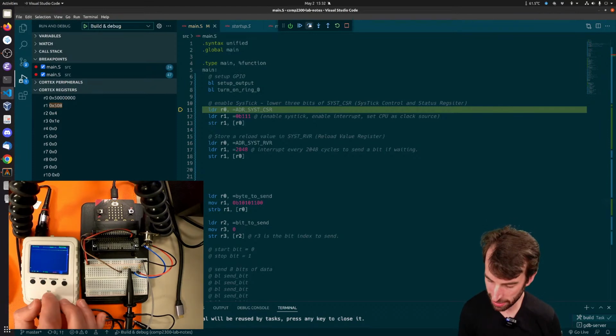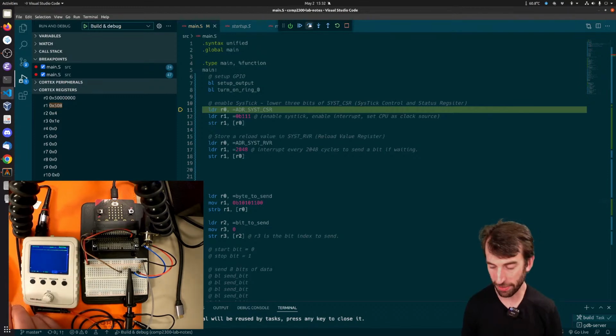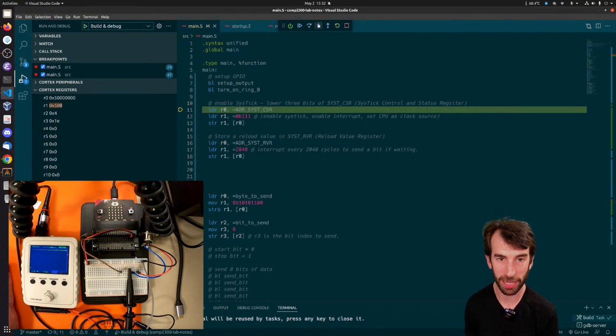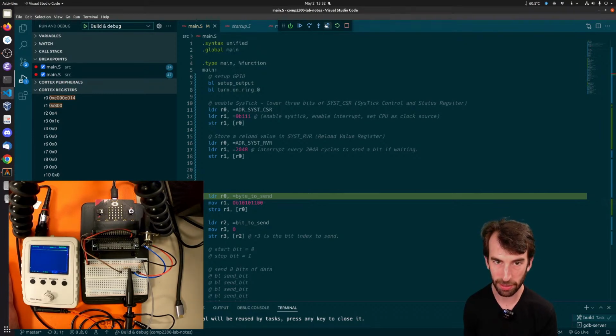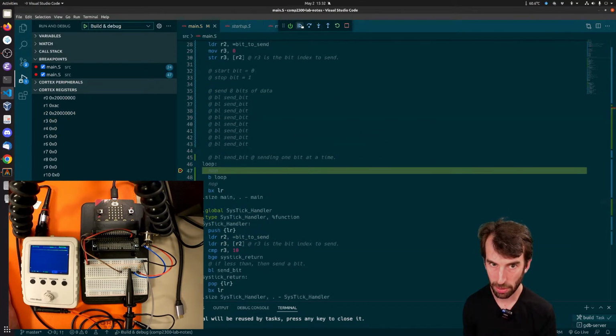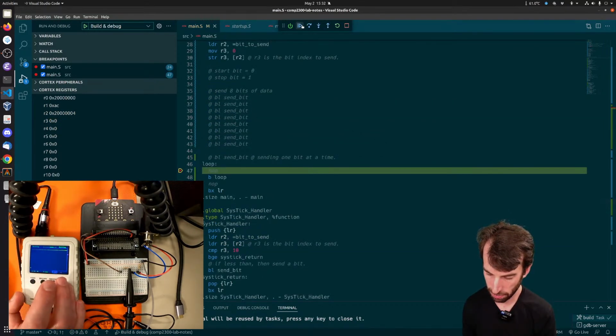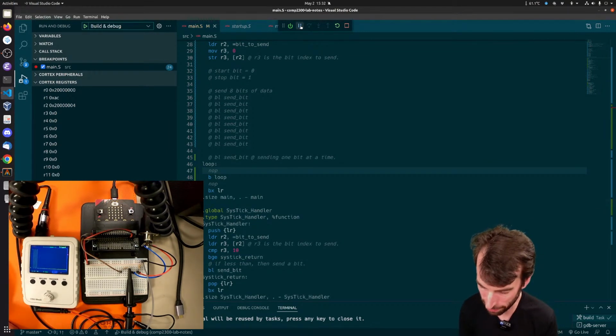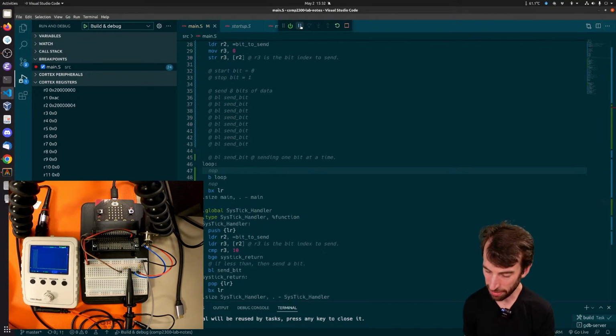Okay. And right now I'm just going to change my trigger so that if I get a downward bit, my oscilloscope's going to notice and just record that data for me. So I might just press play to get to there. Still nothing. I don't know, it hasn't noticed it. I'll keep stopping, that's why. Oh, there's my byte coming out. So it did show up there, but I don't have my start or stop bit set up.